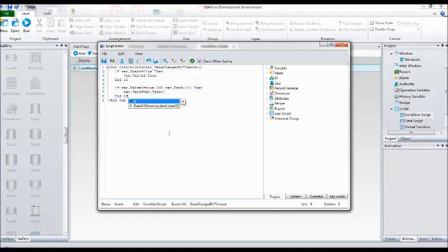This portion is called the filling process. If you press the start button, val1 will blink. That indicates that liquid is going inside, and variable tank is getting increased by 1 every time. Now filling is initiated, and it will complete.